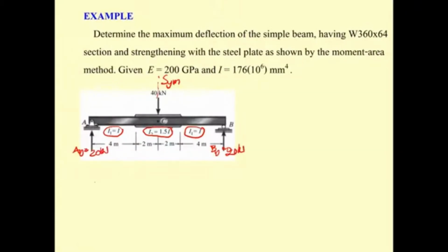And the shear diagram, oh, very simple. The shear diagram is going up for plus 20, and there is no distributed force, so S equals 0. Then up here, the load takes you down by 40. So it's going to be plus 20 minus 40, which is minus 20. And then there is no W, so S equals 0, and you finish this. Okay.